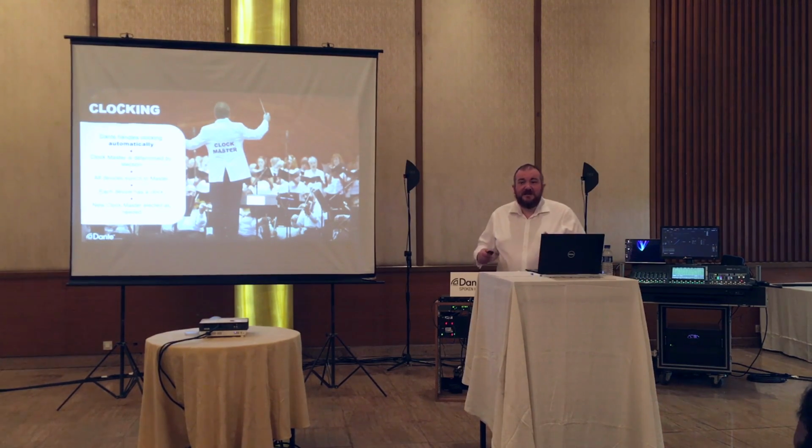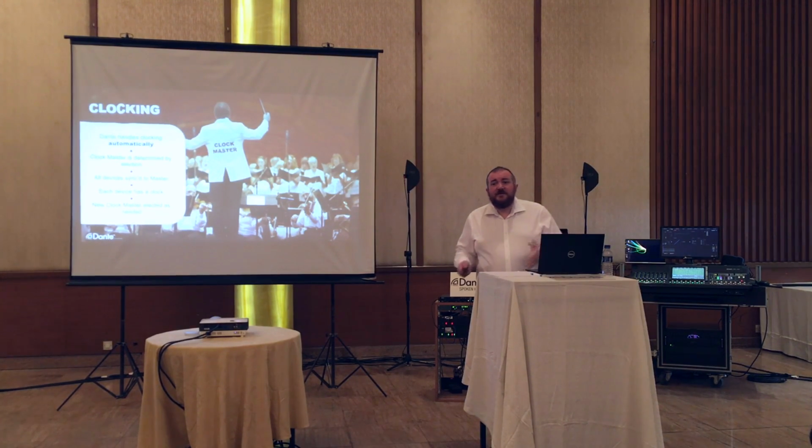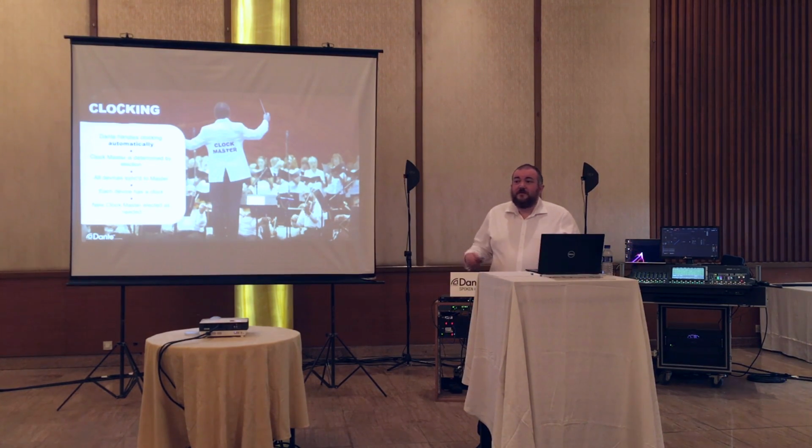So leaving it in automatic master mode is actually much more resilient than having a single master clock device. Now, there are circumstances where you might want a single master clock, of course, if you're trying to do broadcast video and you have to synchronize old-fashioned cameras using Black and Burst with the audio network, sure.